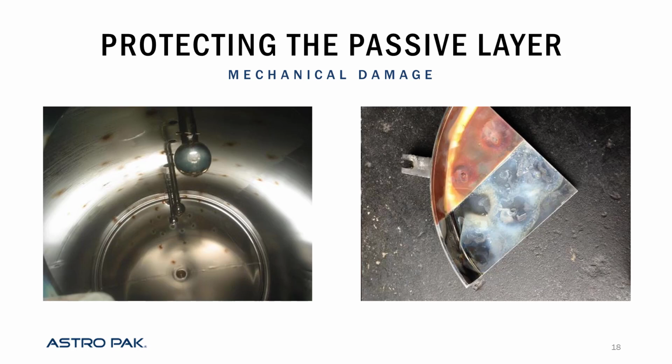These are both examples of ambient water. It's purified water, so there's arguably more corrosivity than with tap water. But the 2 to 10 nanometers of chromium oxide, that can be mechanically worn down. Both of these instances were when a pump was replaced and the horsepower is different than before, and they got too high a flow that exceeded the spray ball manufacturer's recommendation. So definitely always keep in contact with your spray device manufacturer to make sure what's their highest pressure or highest flow out of the orifices.